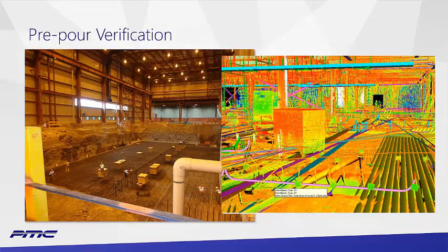Pre-pour verification is very good to have done before you pour concrete. Make sure that all your piping and everything is laid in the correct locations and that you have a record of what you're about to bury.